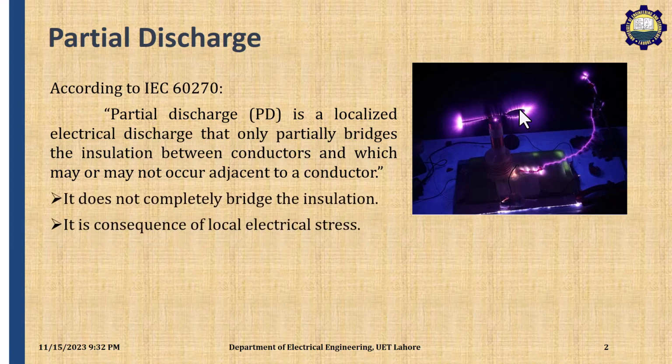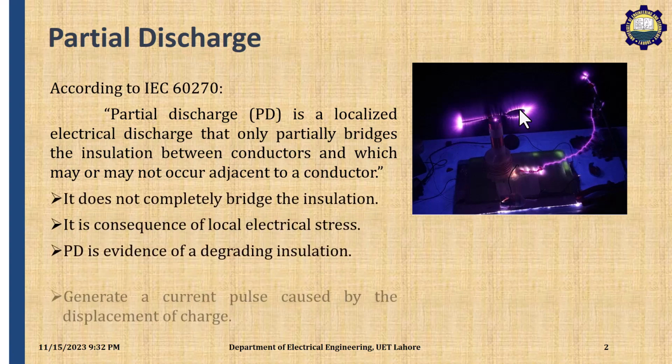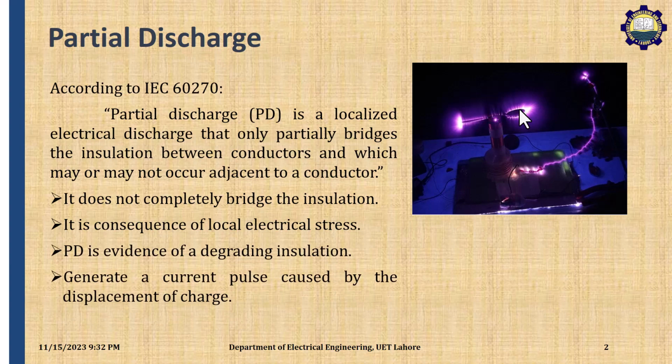Further, it does not completely bridge the insulation. It is a consequence of local electrical discharge, and PD is evidence of degradation of insulation. When PD occurs, if we are discussing a cable, the insulation of the cable will degrade or its life will decrease. Whenever a partial discharge occurs, it will generate a current or a voltage pulse